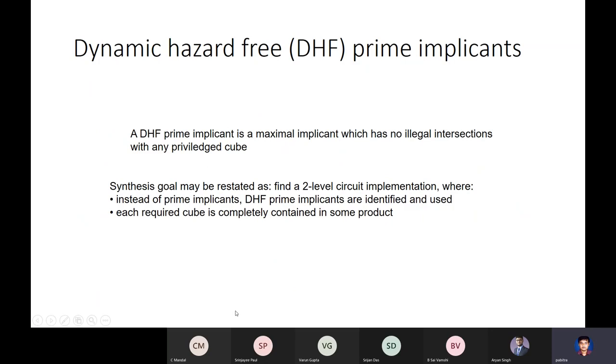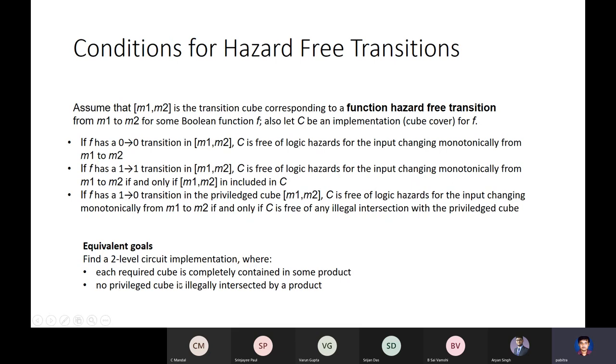So to do this, what we do is, you remember your Quine-McCluskey method or the Karnaugh map based realization. To have a minimal realization, we identified all the prime implicants, the essential prime implicants and others. Then using the Quine-McCluskey chart or just the Karnaugh map, we find the set of prime implicants which cover all the minterms or positive minterms, or maybe the don't cares if they are there.